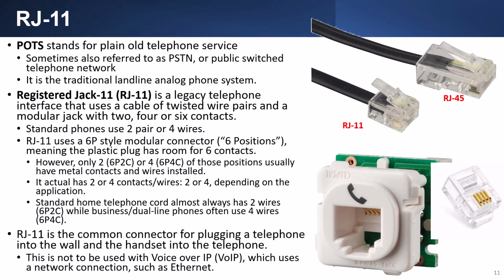POTS stands for Plain Old Telephone Service, sometimes also referred to as PSTN or Public Switched Telephone Network. It is the traditional landline analog phone system. Registered Jack 11, or RJ11, is a legacy telephone interface that uses a cable of twisted pair wires and a modular jack with 2, 4, or 6 contacts. Standard phones use 2 pairs or 4 wires.